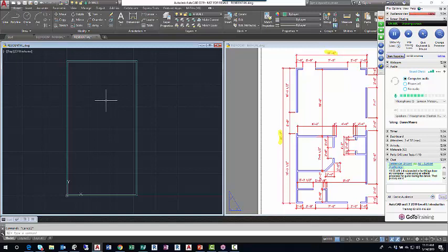What that allows me to do, exploding those two rectangles, breaks up the rectangles, or polylines I should say, into 8 lines. And now these lines can be offset independently of each other, which I really want. In the beginning, I wanted to offset a rectangle and get a rectangle so I could have the appearance of a stud wall, but now I want to offset lines and get lines. I want to create cutting edges to make window openings.